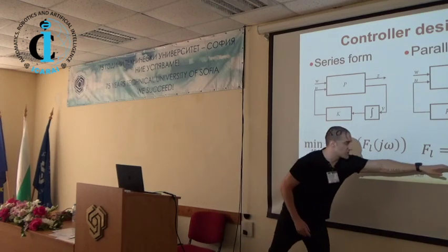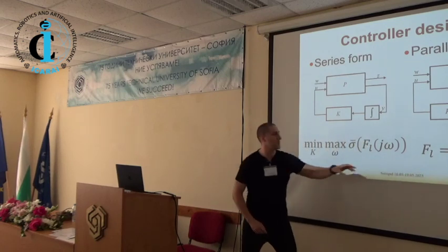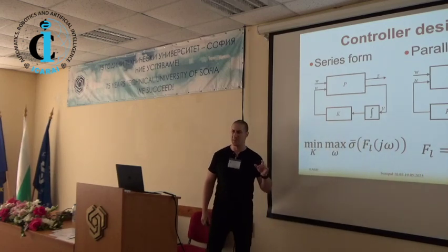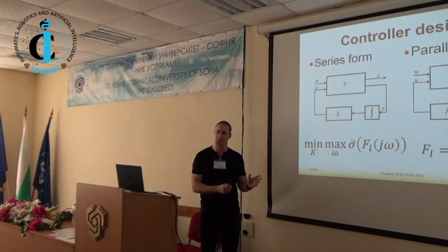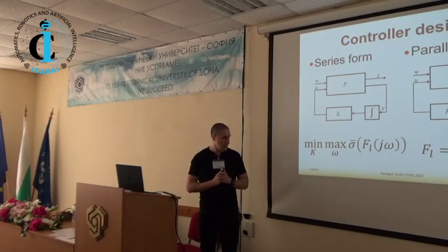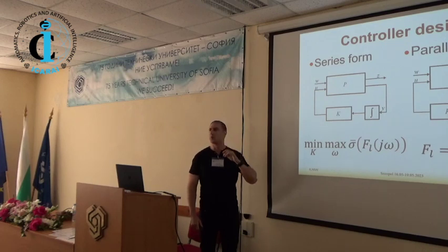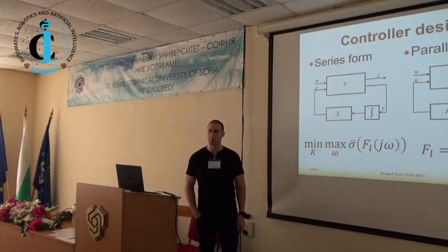And for the control signals, we try to have around 40 decibels in the low frequency range. In the high frequency range, we decided to decrease it by 20 decibels per decade until we get to 20. You obtain a very nice result without oscillation.